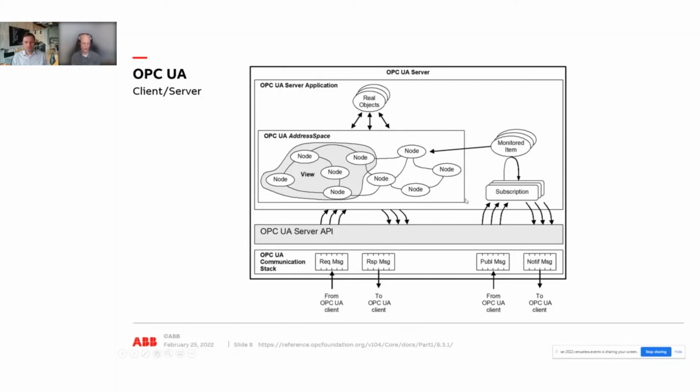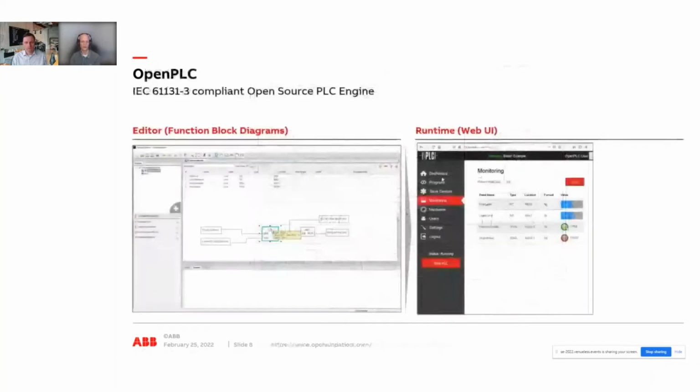And we utilize OPC-UA also for the state transfer, because the protocol is deployed anyhow. So we just take the nodes and their current values and then transfer that to a separate OPC-UA server, as we will see right on.